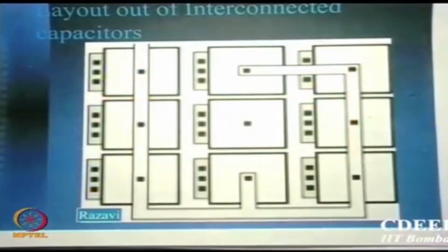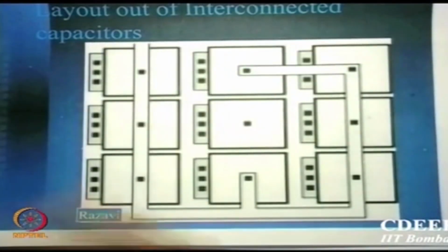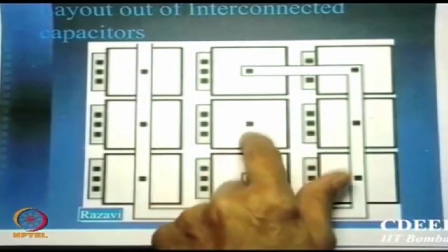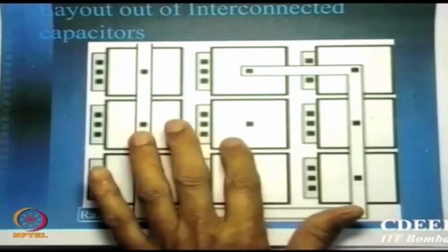Now, it is also decided that the capacitor should be closest to the point where the node capacitance is to be created. Otherwise parasitic capacitance will actually shift our poles or zeros. So in analog, the position of the capacitance depends on which node you are actually looking at, and you bring your capacitances closest to that. Instead of having one large capacitor, you can create small unit capacitors and then connect them in a fashion. But do you see this capacitance is not connected to anywhere?